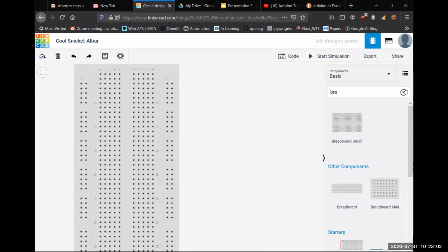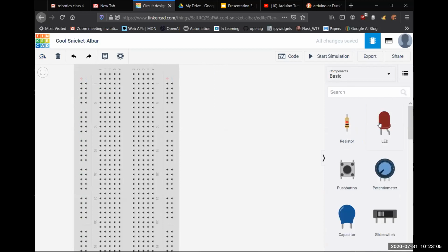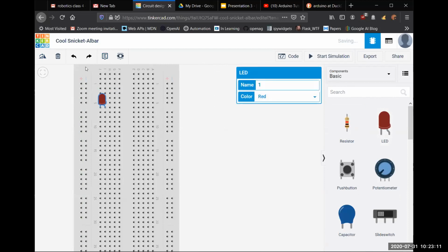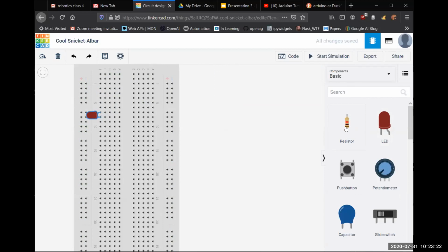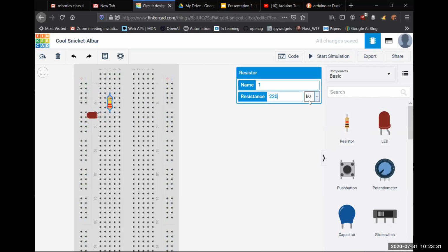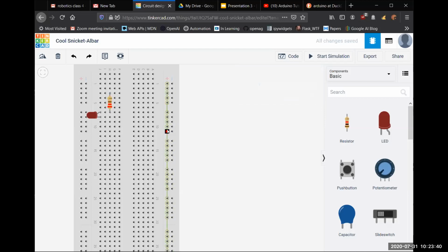Okay, so after that, you're going to grab our LED. Make sure you know the direction when you're doing the connection. There's the long leg and then there's a short one as well, like this. So remember to check the long leg and the short one, and then you'll grab your resistor. When you check the color codes, make sure you're using a 220. For the LEDs we're using, 220 is sufficient for what we are doing at the moment. So make sure you always grab 220, red and brown.